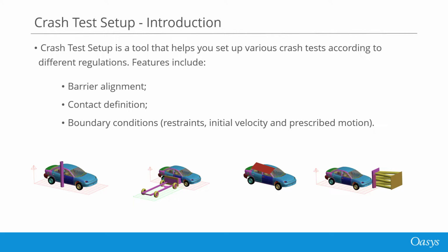The tool can be used to set up a single crash test relatively quickly, but is also designed to improve the process of preparing multiple crash test models. You can define all of the required settings for a vehicle and link them to a keyword file. Then when you read in the model again to set up a different test, the settings are automatically loaded.